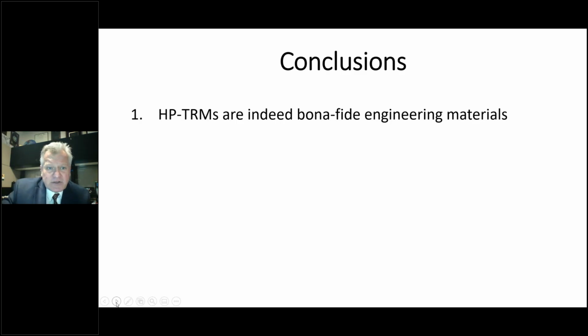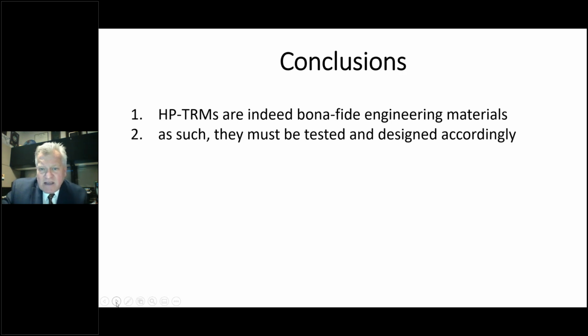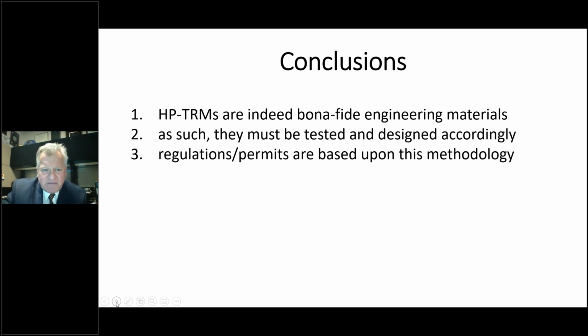So in conclusion, HP-TRMs are indeed bona fide engineered materials. As such, they must be tested and designed accordingly to give a factor of safety. Regulations and permits are based on this methodology. I see that used in both EPAs and DOTs throughout the United States, and for that matter, the world. Obviously, big users of this are the Corps of Engineers and Bureau of Reclamation.